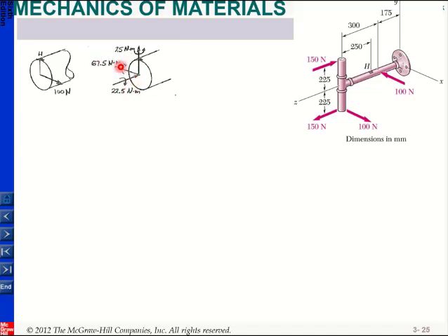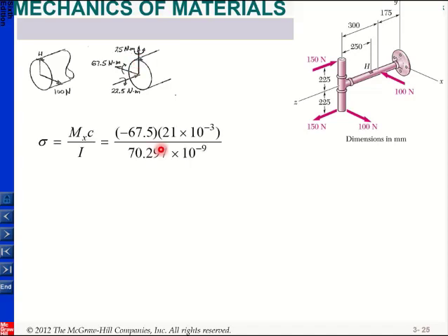It goes to the minus x direction, and I know that at the end I will get compression. So this is your equation for normal stress, you will get compression, M_x c over I. Since it's circular, your I_x or I_z or I_y are all the same, so you just have one I. And then if you write it, this is how you get your sigma.